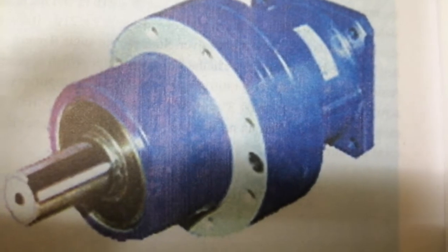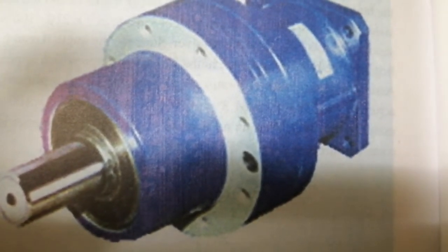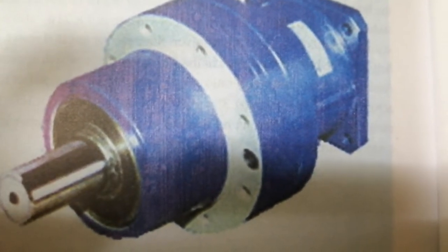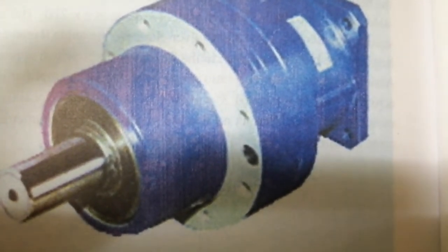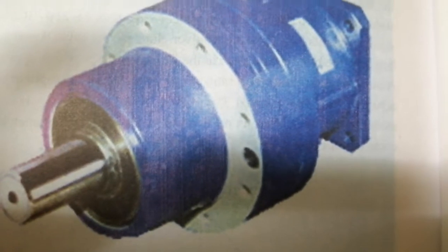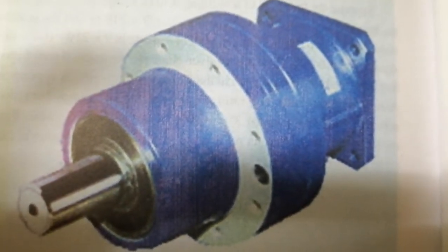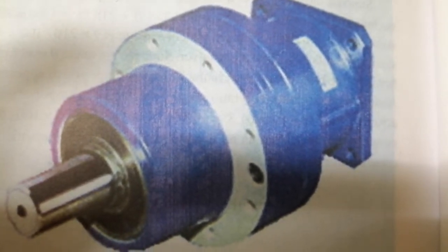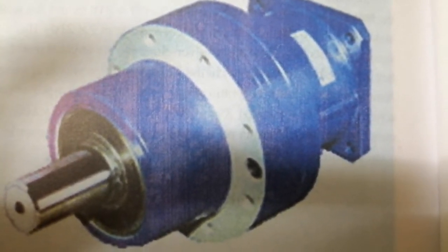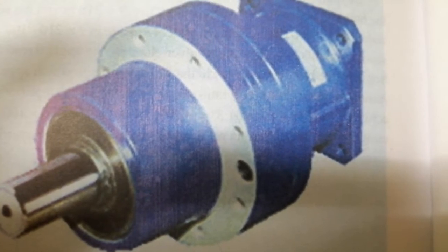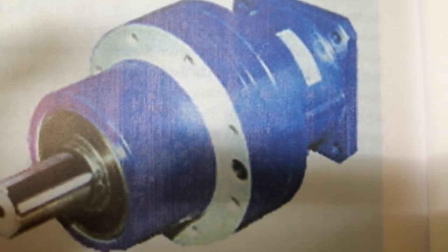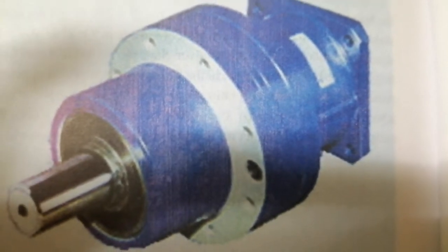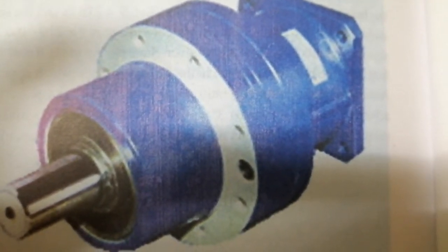They generally operate at very low speeds or sometimes zero speed, or they may operate at a very high speed. So a servo motor differs in application capabilities from larger industrial motors. So what are the differences? They produce high torque at all speeds including zero speed. This is the main feature of this motor. It can be operated at zero speed.